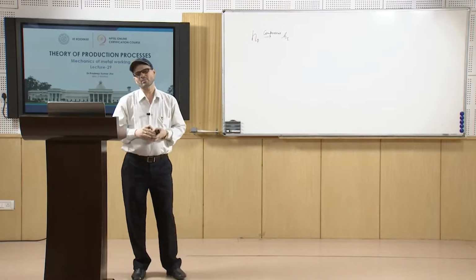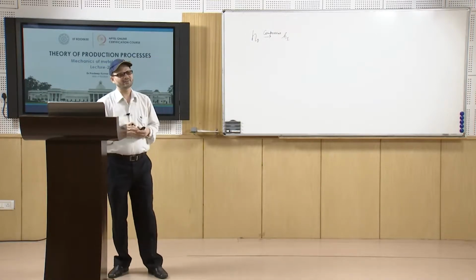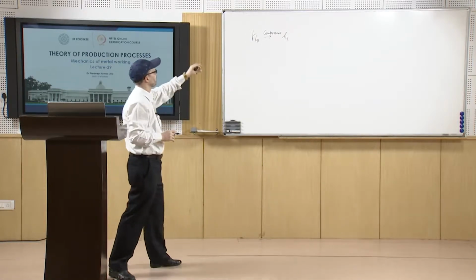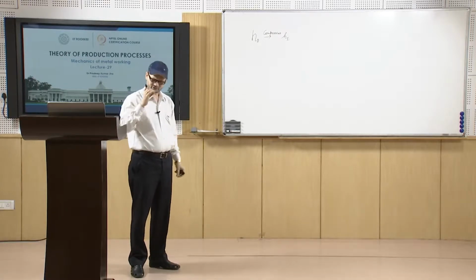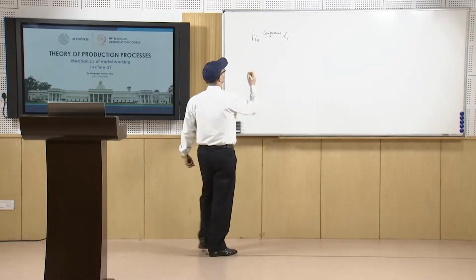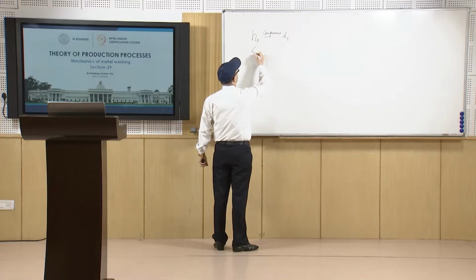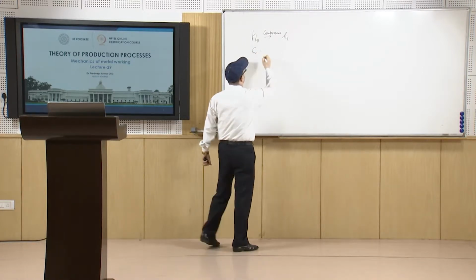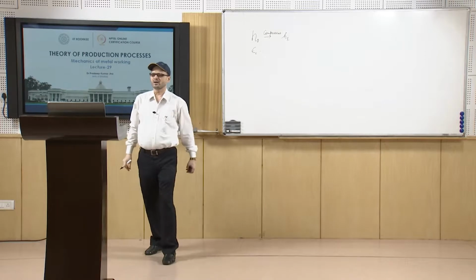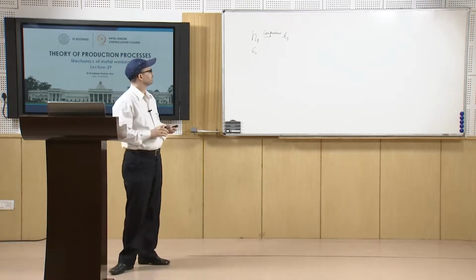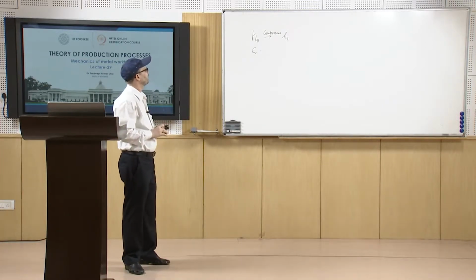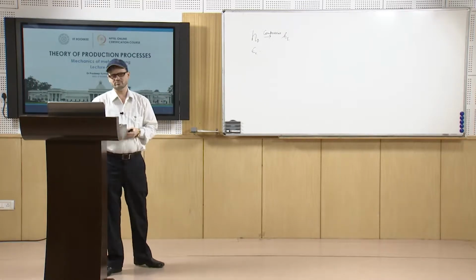In that case, if you try to find the compressive strain, taking the true strain value, the true strain in compression will be ln of h1 by h0.